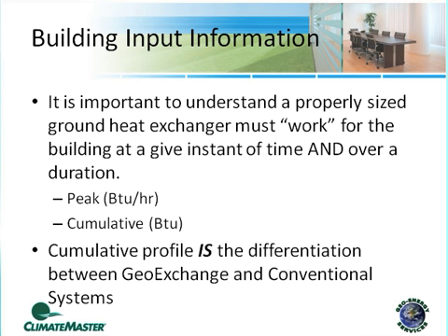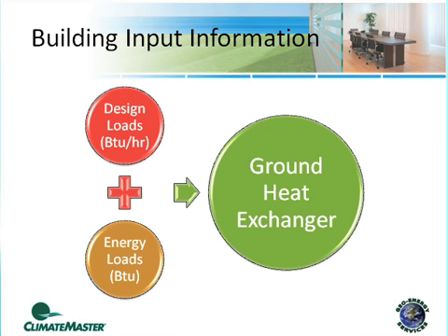So even though I've got an identical building that may have an identical peak BTU per hour heating or cooling load, if I don't understand the cumulative effect and how that building's being used, I'm going to miss the mark on my borefield design. And it'll either be under-designed or over-designed. So you're either going to spend more money than you needed to if it's over-designed, or you're going to be in a lot of trouble if it's under-designed because you're not going to have systems performing right. So it's critical to understand not just one, but both of those components on the inside of the building.